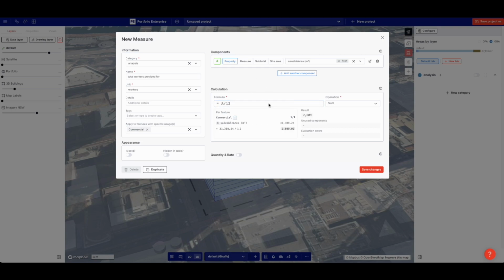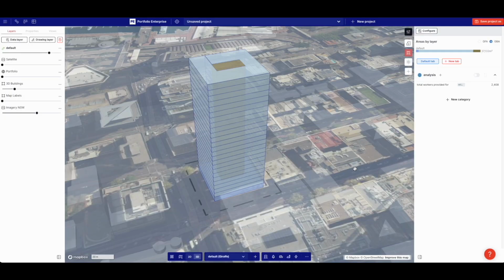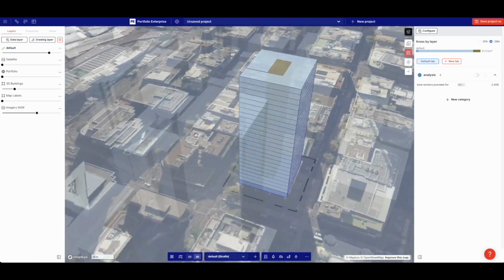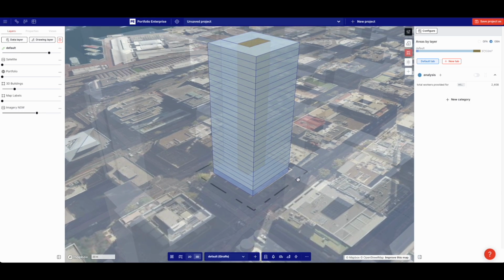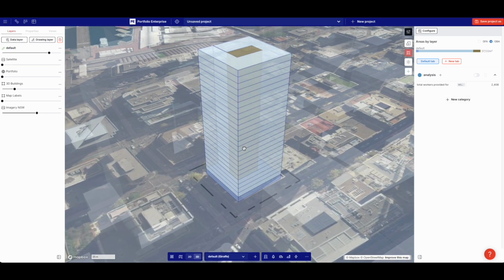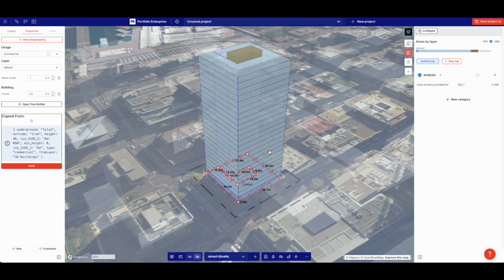And say, in discussion with my board, we're going to allow 12 square meters per worker, or maybe 14 square meters per worker. And if we do that, you can see, hey, we can allow for 2,400 workers in this building. So this is, you know, worth considering. Now, what you could say in the meeting is we know that with work from home, that 2,400 is going to lower. So what we may want to do is provide a couple of amenity levels.